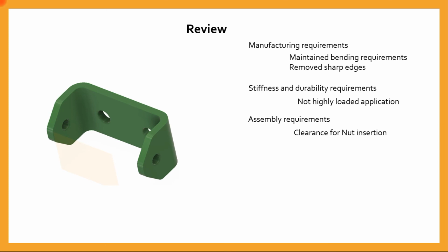Second, stiffness and durability requirements. Since this application is not a highly loaded application, the only thing which matters is the stiffness of the bracket and not the durability or fatigue life of the bracket. So that is already maintained. 2 mm is sufficient for the application.